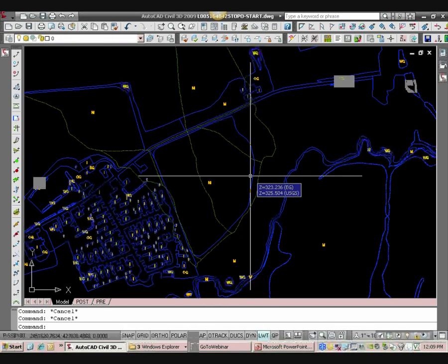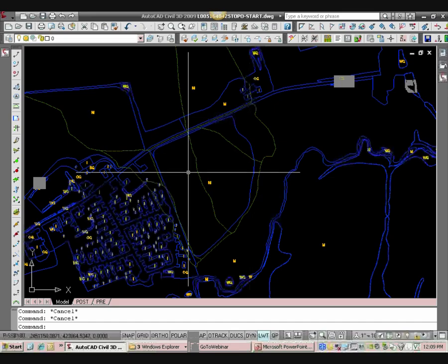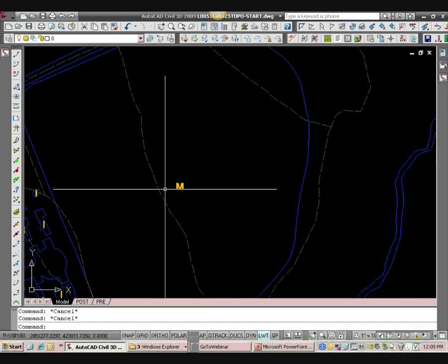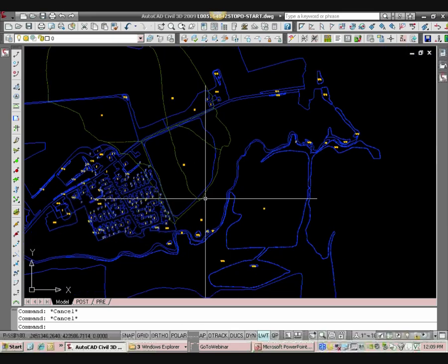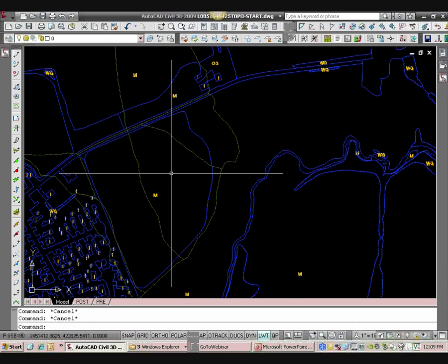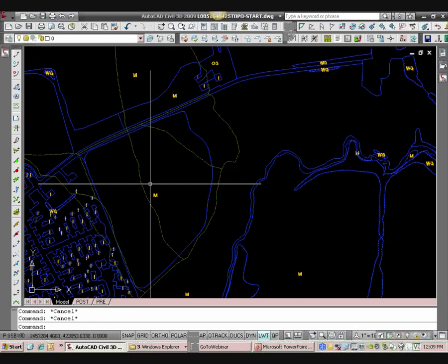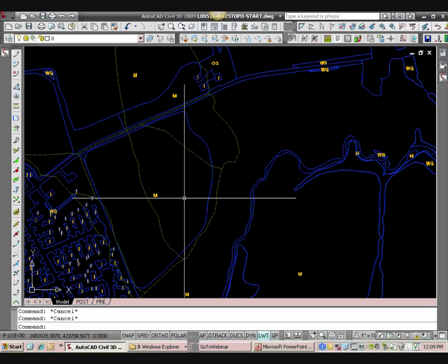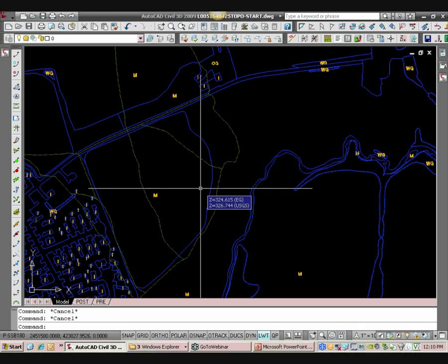This is the pre-development for the site. We're going to develop this area right here, and right now it's meadow. This is basically what you're looking at as a topology. That topology lets the computer know what areas are what, and with that, you can overlay all these things and get a curve number fairly quickly.